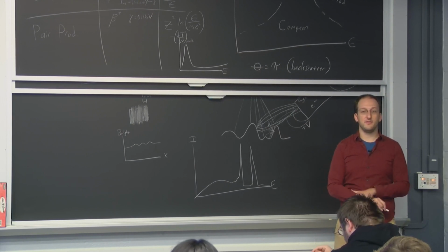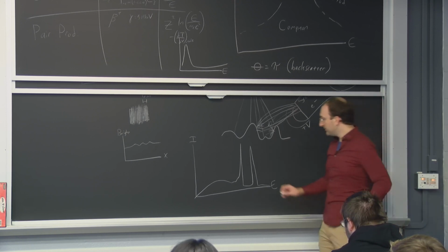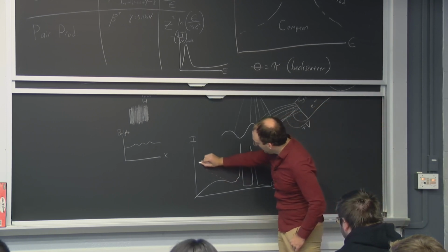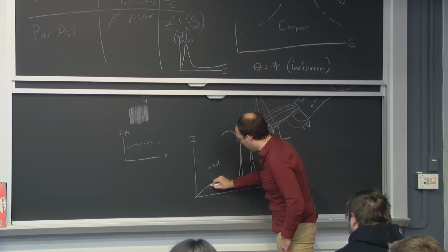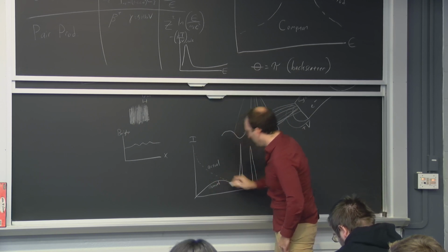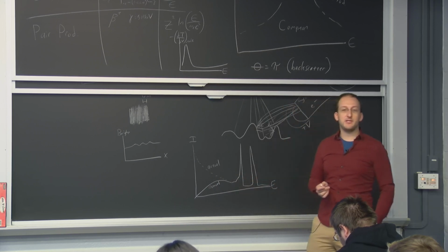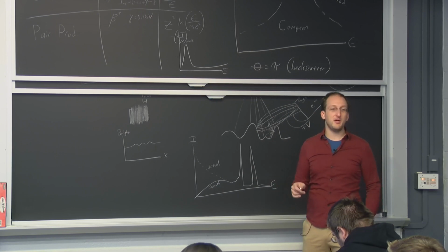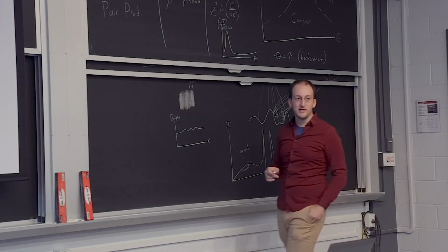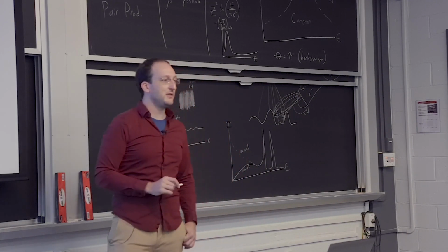Doesn't it sort of look almost like exponential decay, or like something that starts out at very high intensity and then goes down? That's right. You actually should get more low-energy Bremsstrahlung. One of the reasons you don't is that the lower the energy of those X-rays, the more they get absorbed, self-absorbed in the material, in the few gas molecules in the SEM, and in the window of the detector. So just because this is what you see doesn't mean this is what's actually going on in your material.